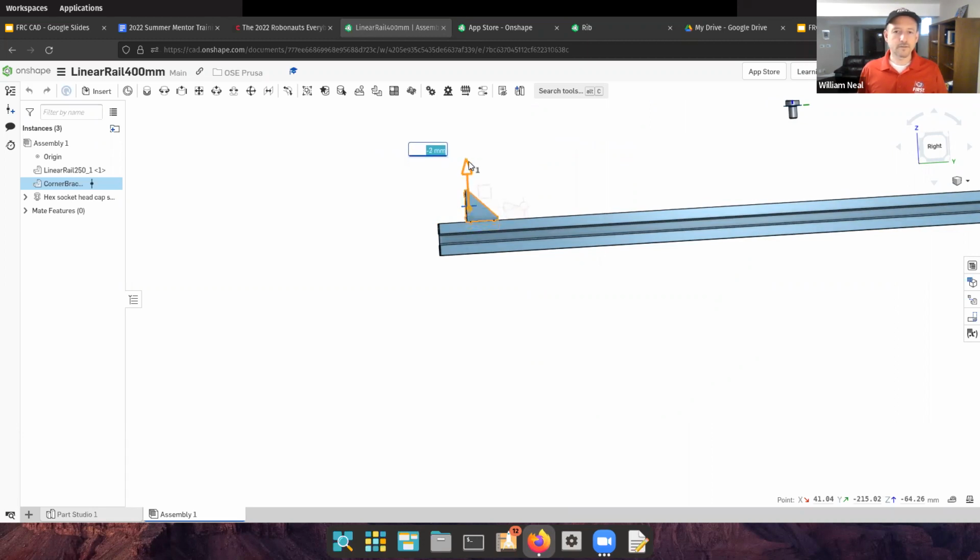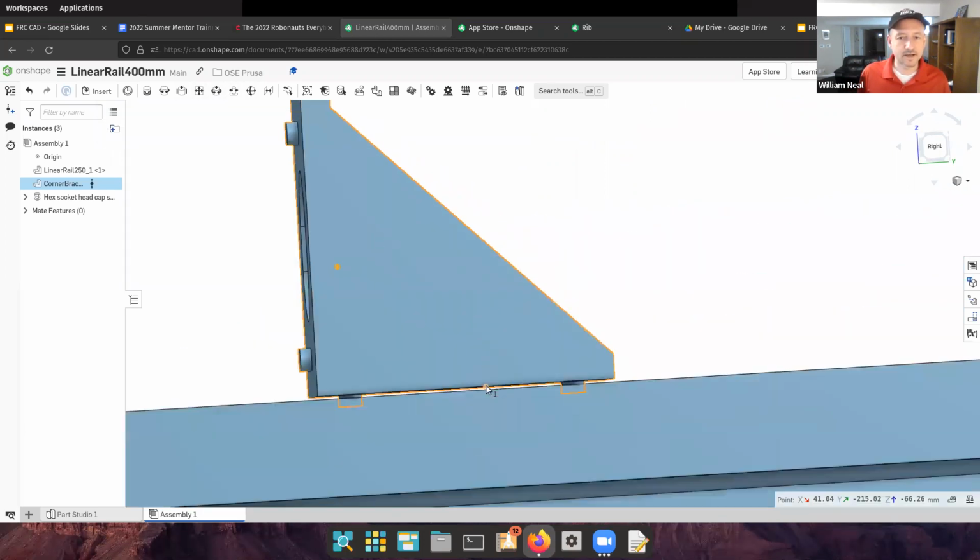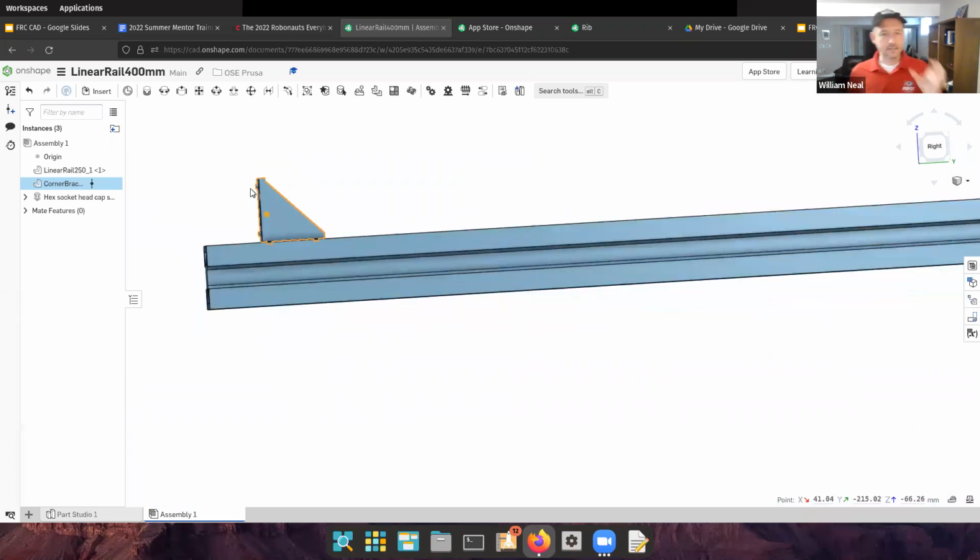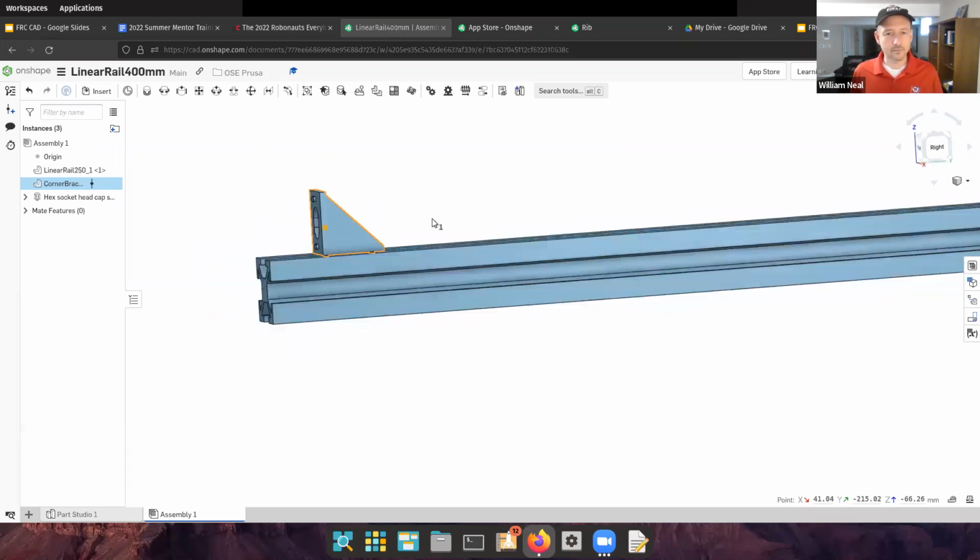There are lots of little features that can be added or sort of tricks that we can do. We can snap it and we can say that it's mated between planes, for example. So I can specify that the bottom plane of this part is connected to the top plane of that part and gradually assemble these things together and snap them nicely done. So maybe I can try that in another part here.